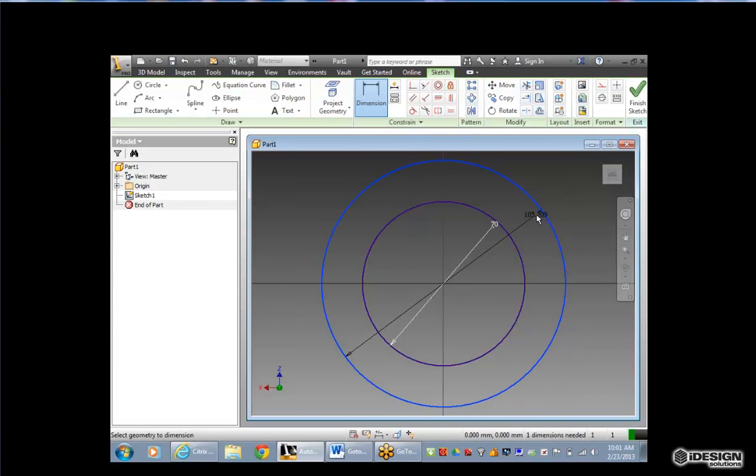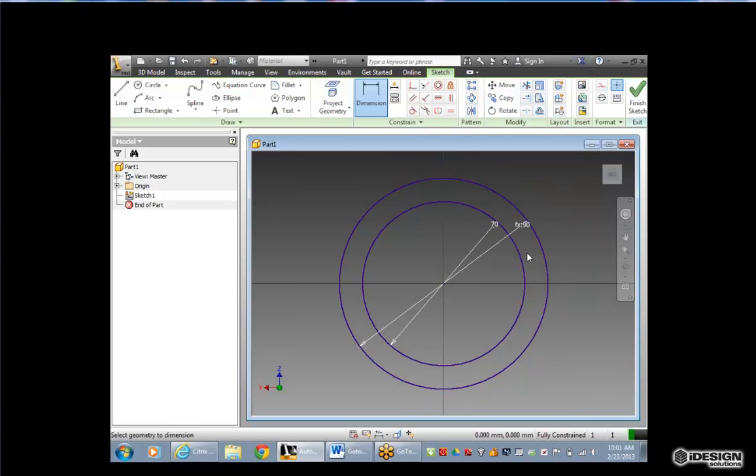Okay, and then we dimensioned the outside circle at what? Well, now when you have the dimension, you simply left-click to place it, and now you want to click on your 70, and that'll give you the reference, and then you type in plus 20 millimeters. That didn't happen. Okay, so put the cursor into the field where the dimension currently is. This one? Yeah, so right now you're in dimension 2, right? So if you click on that 70, it'll say, okay, he wants it to be that dimension. So now type in plus 20 millimeters or plus 20. Got it. Okay, cool. So it made it a relationship as opposed to a static number. It's 20 bigger than the inner circle.